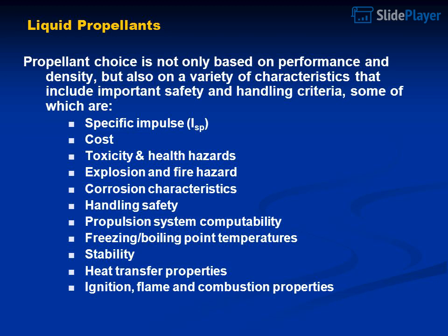Propellant choice is not only based on performance and density, but also on a variety of characteristics that include important safety and handling criteria, some of which are: specific impulse, ISP, cost, toxicity and health hazards, explosion and fire hazard, corrosion characteristics, handling safety, propulsion system compatibility, freezing/boiling point temperatures, stability, heat transfer properties, ignition, flame and combustion properties.